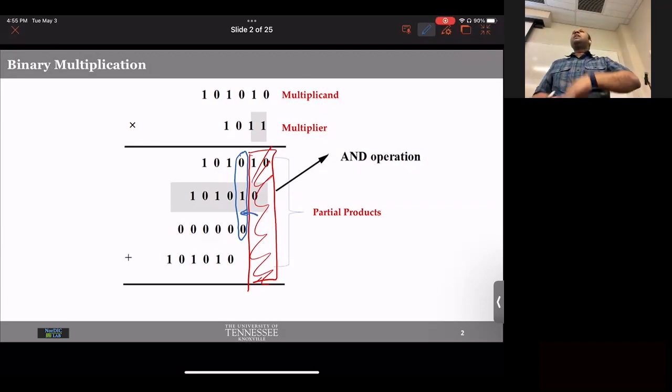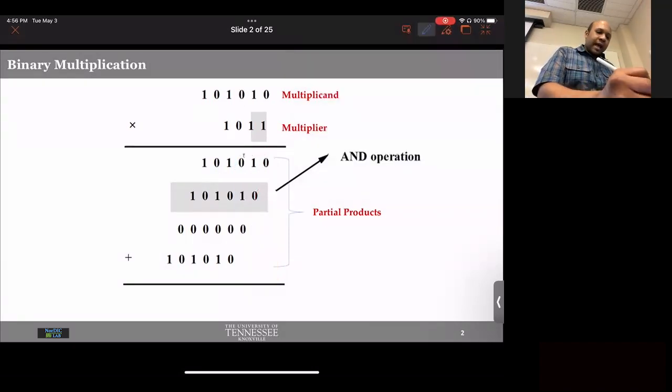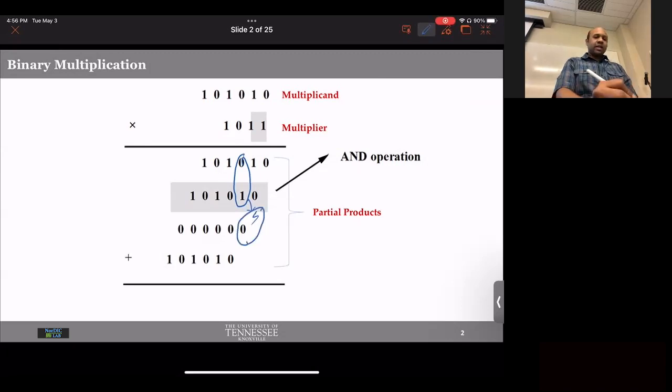So essentially, you are dealing with 4 inputs, 1 carry and 3 inputs. Can you do it in one stage? No. What should you do? You should first add these 2 numbers using an adder and add that sum of that adder to the next bit, and then you get your result. Am I making sense? Folks, are you guys confused or are you with me? Okay. Online folks?